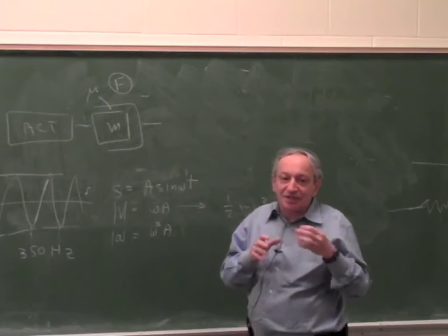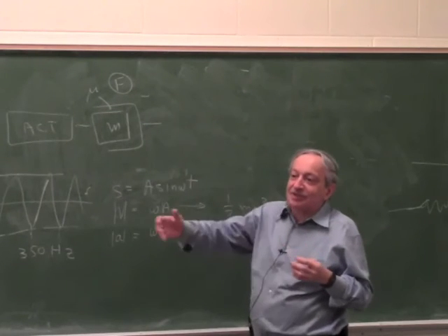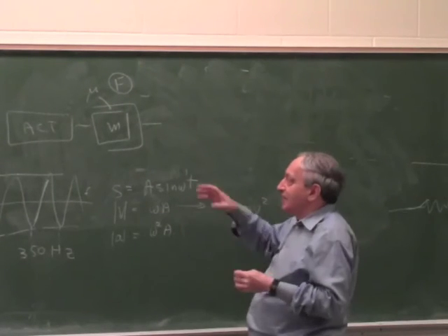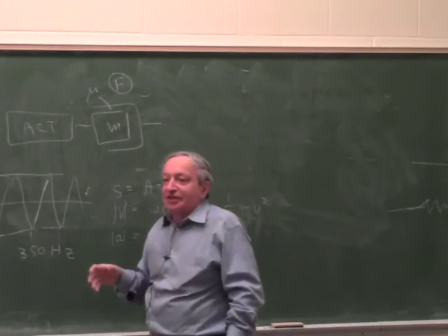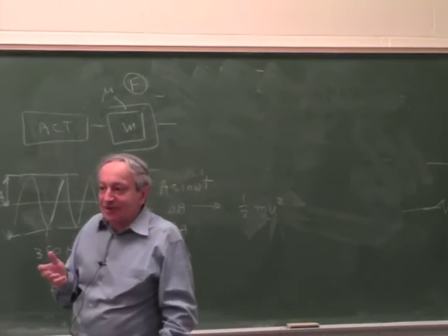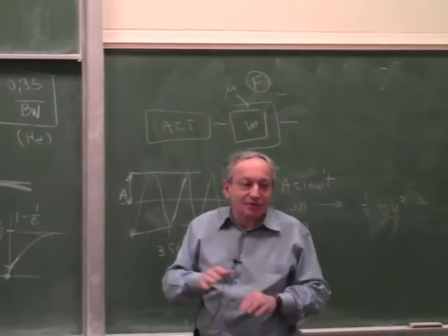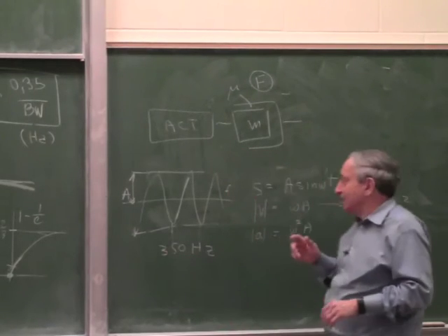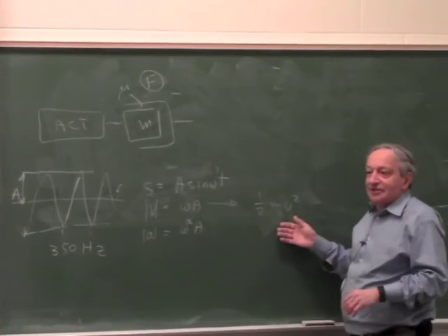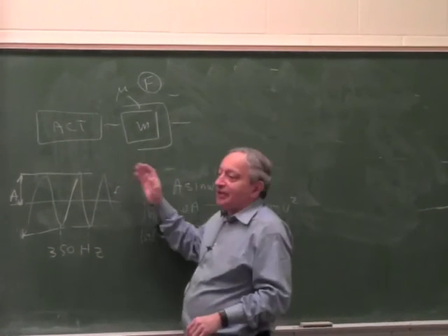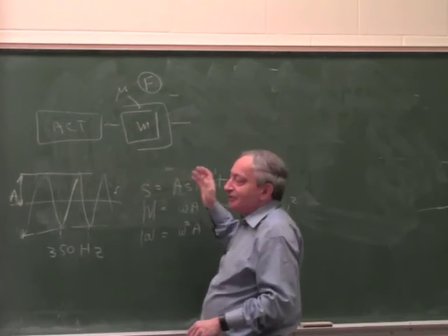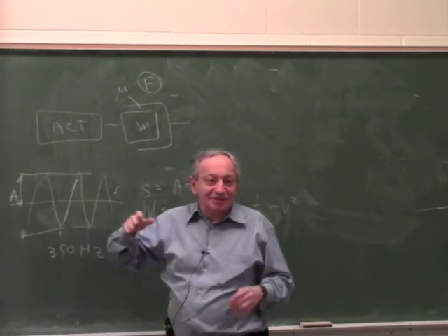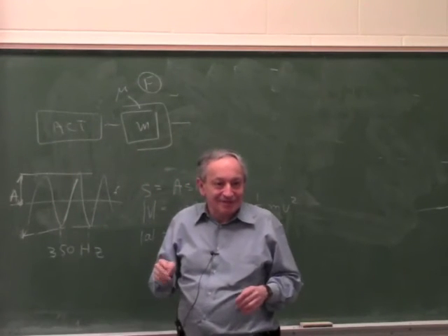If I have a mass and a spring, all this is recoverable. But this ties to the question in a servo, does it have regenerative braking or not? Since most simple servos don't have regenerative braking, to the servo this energy is not recoverable. You have to accelerate the mass all the way, and you can't count on it coming back, like with a spring.